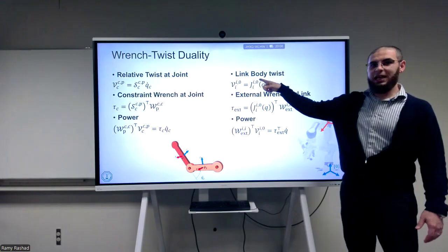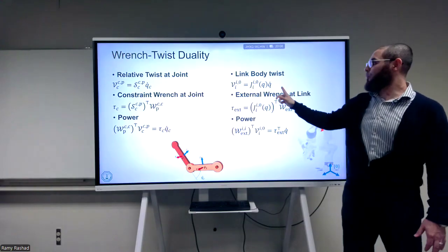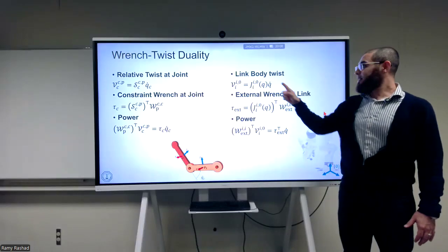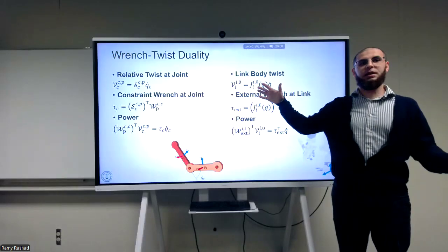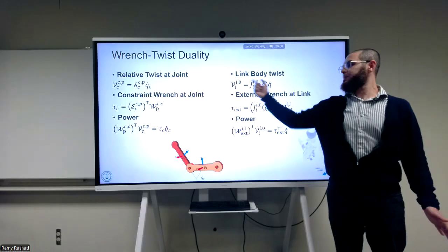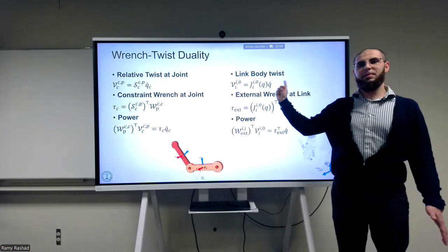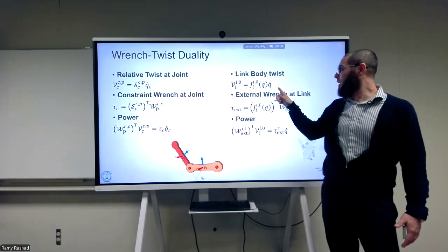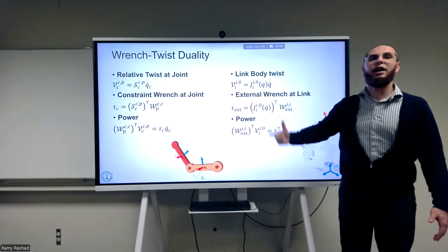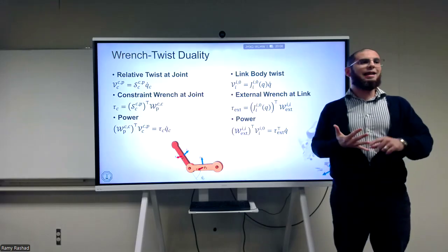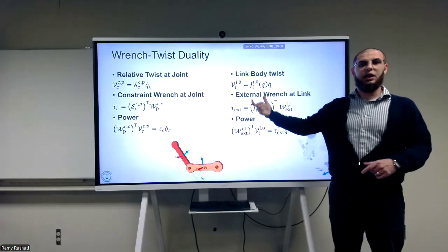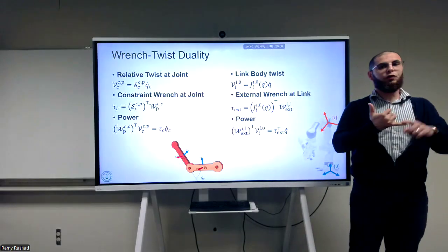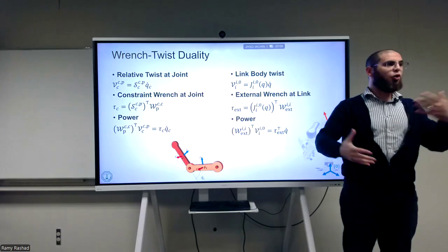Here, this is general. What's inside of the J here? The J is a map from the q dot to the V, which in the end are the tau external and the V. This is a linear map between two vector spaces. If you really want to know what will happen when mapping from here to here, you need to analyze what's known as the kernel and the range space of this J. And you start to go into all of the stuff that I mentioned about the maneuverability and the manipulability of the robot and so on and so forth.